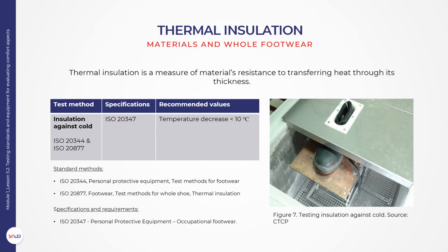keeps the heat generated by feet. The heat supplied in cold conditions can fall to very low values, being important to keep this heat inside the shoe. Standard methods are available to evaluate the insulation of footwear against cold, to be used in very cold environments. Basically, in this test, footwear is placed on a copper plate in a cold box at very low temperatures, for example -17°C during 30 minutes.